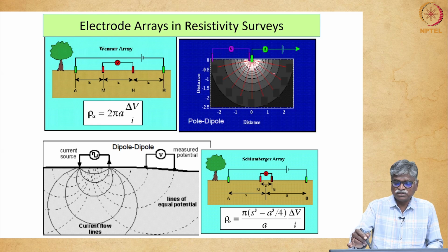Every meter, if you put in 1 meter, you will get that 1 meter information. If you put in 2 meters, you will get the 2 meter information. If you put in 3 meters, you will get that information. Information means you will get the resistivity of the particular depth. Then we have to plot the same readings for whatever depth is of interest for the investigation.